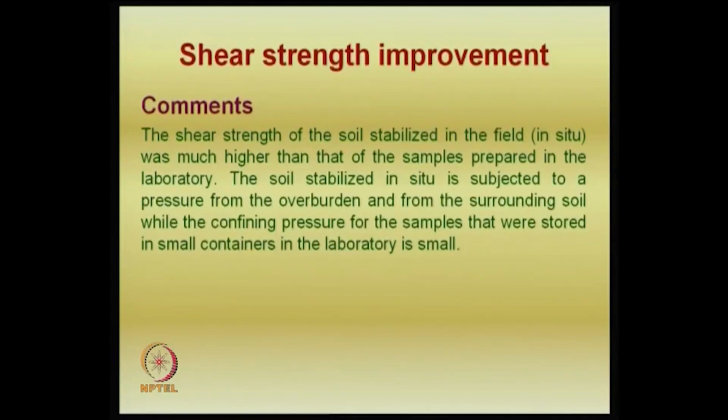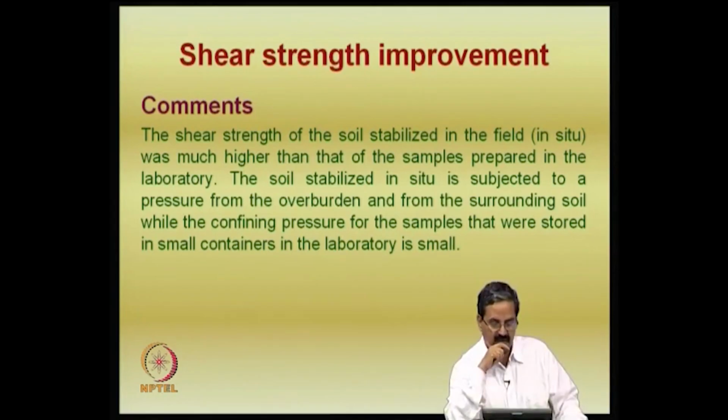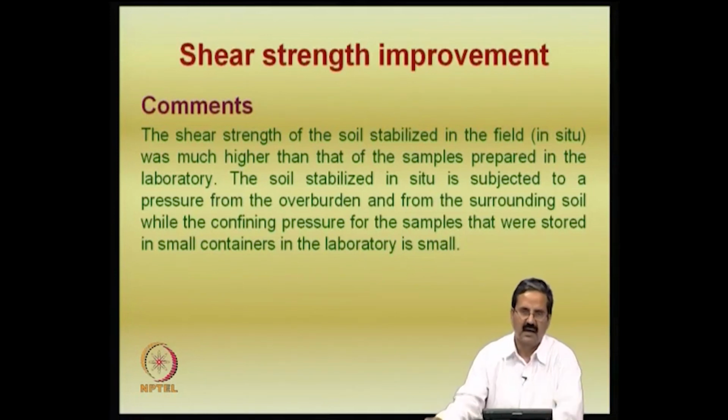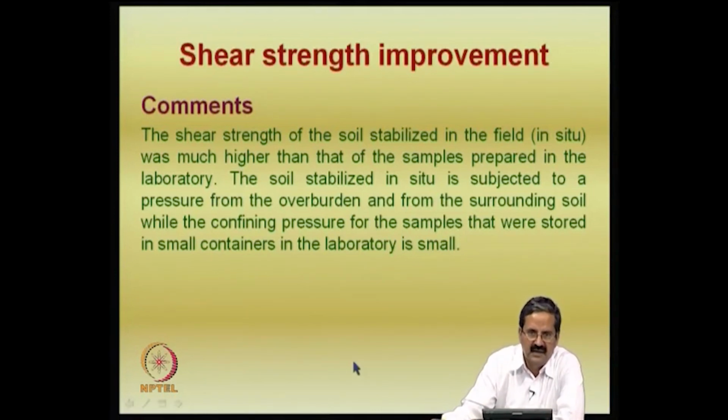And how is the strength of the soil improved? People have seen, like you have seen just now, that the CBR is nothing but the strength of this in situ soil, and when you add lime, the strength of the soil is increased by about 30 times, 40 times, 15 times in some cases. In situ CBR tests were done in some cases, and we have seen that. You also saw the results of the unconfined compression tests from Professor Prabha, where it was very clear. Even in our lab we have a lot of experimental results where it was very clear that the treatment using lime produces strength improvement.